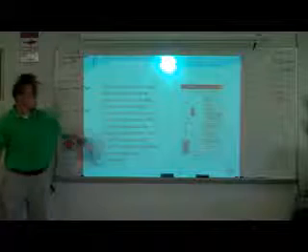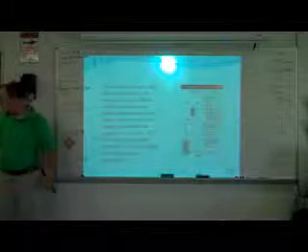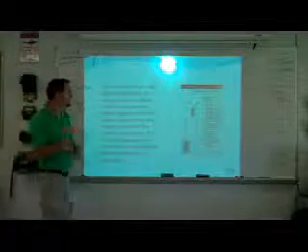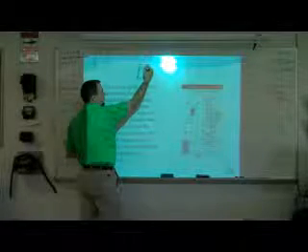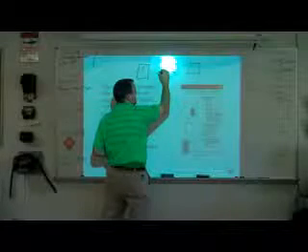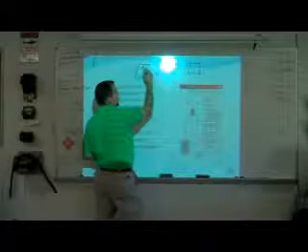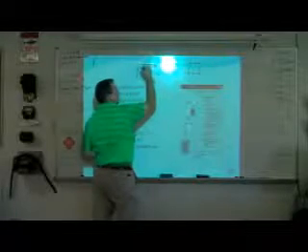The 10-foot tap rule permits tap conductors to be supplied from a feeder without overcurrent protection at the point where they receive their supply power, provided 5 conditions are met. So what they're talking about, the 10-foot tap rule: if I have a panel here, and I have a panel not more than 10 feet away, I don't need to go through this, then over. I can just come in, and right back out and over. That's a 10-foot tap. Okay?